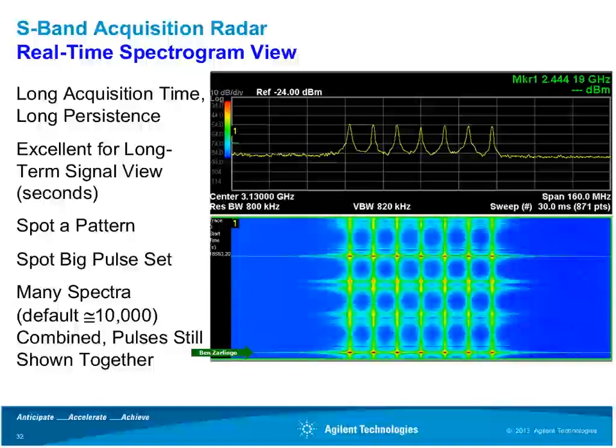So a very challenging signal to measure because it's got a low duty cycle and it has one aspect of its behavior over time that has a fairly long time constant. That is, the repeat of the antenna rotation is on the order of 5 or 6 or 7 seconds. So there's multiple different kinds of dynamics going on here at once, though there's really only a single signal present.